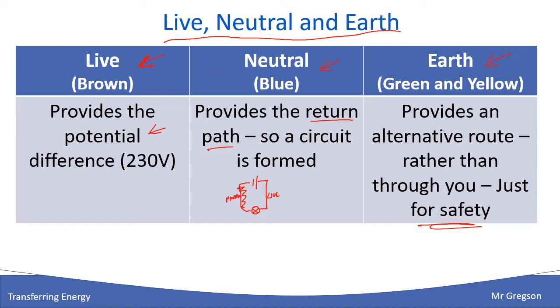Now, occasionally, if we might have some wires going through a metal plate, and if this metal plate, that I'm trying to draw very badly, moves backwards and forwards, the wire starts to rub, and some of the inside of the wire, the insulation, was worn through, and it starts touching our metal plate, which means that this metal plate now is live. This is bad, because if you were the next person to pick that toaster up and touch that, the electricity would go through you back into the ground.